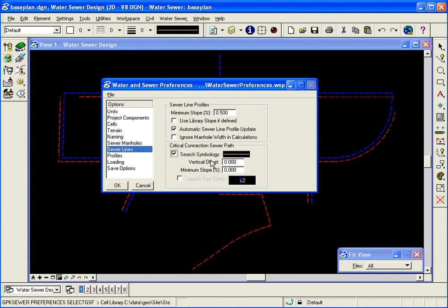And so you draw the path that you would be connecting with, and that would go ahead and do a check and profile and allow you to see if you can actually service that building, given the current grade and depth of the sewer line at the location specified.